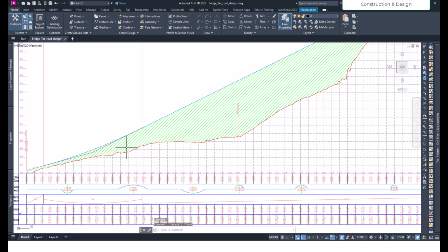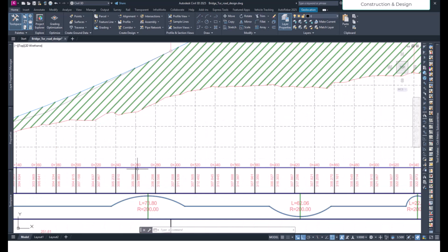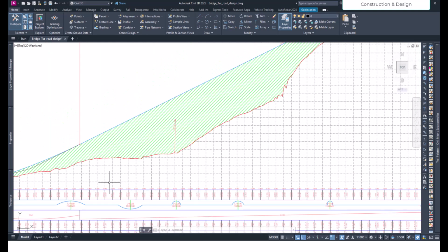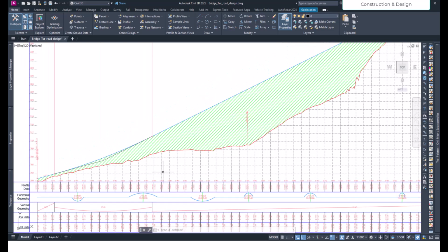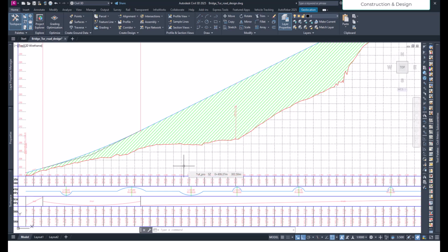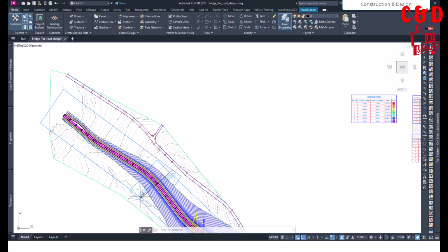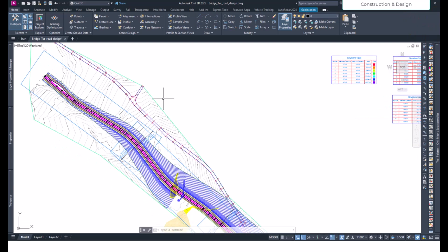So maybe we can start from 240 or 260, depending upon how much you want, and also the soil conditions. If you find good rock, bedrock, here, then you can decide accordingly, and it also depends upon the river and how the river flows. Right now we don't have a river, but the direction of the flow also matters, so we have to check these conditions. For now, we are only concerned about using the default sub-assembly that we have for the bridge.